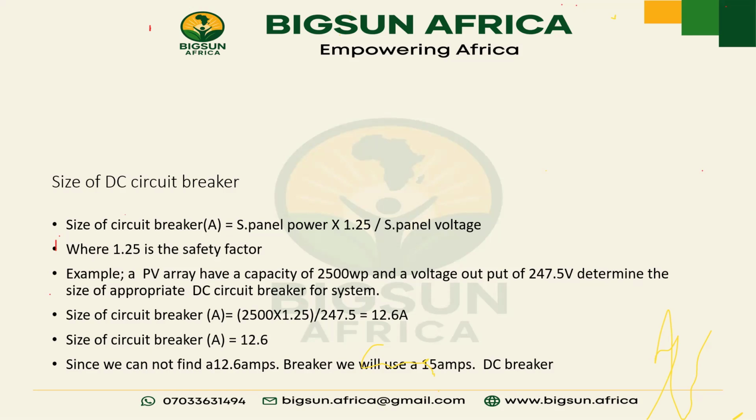So we know where we are, right? Our total power is 6,300 after you have multiplied it by the safety factor. Now we are looking at connecting the panels 3 in series. What's going to be our system voltage now? 51.5 times 3, which is 154.5.